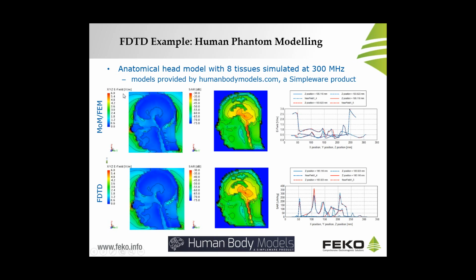You have the electrical near field, also the SAR here on the row above for the hybrid MLFMM and FEM method, and on the row below for FDTD. You can easily see that the results agree very well.